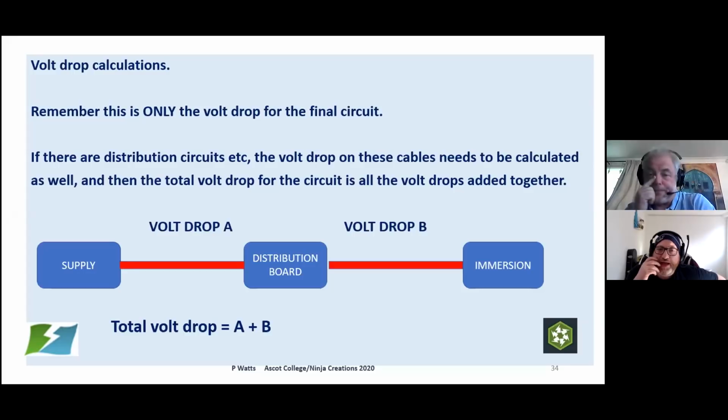Okay, Kevin says you'll need to ensure your tester is at the same ambient temperature as the circuit under test. Taking your MFT from a cold van to a warm house could give you a 20% difference. Yeah, it's true. I've actually seen this where I've got an early morning cold instrument, and as I start using it, the values start to move. It's a good point.